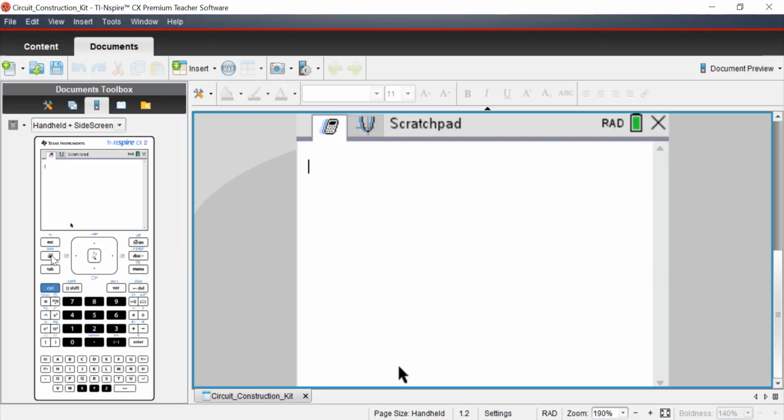So if I'm going to pull up my little calculator screen right here, and we said that we can manipulate the equation so that it looks something like this, V divided by the letter I, and that's exactly what we're going to do. So we know the value for V, we know the value for I, so then we're going to go ahead and plug those in. So 9 volts divided by 0.9 amps gives me 10 ohms, which is the unit for resistance. So it's spelled like this, ohms. And so now I know what my resistance is. That was what's called a 10 ohm resistor.